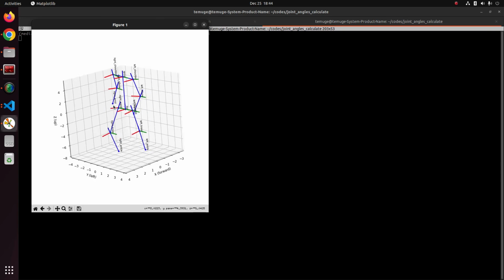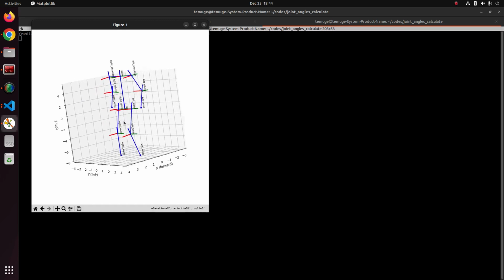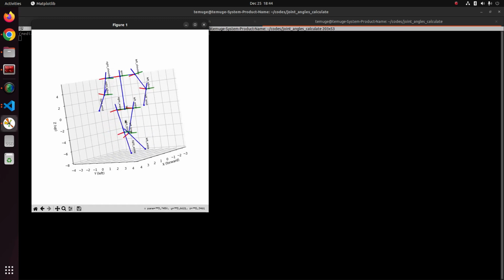Here we can see each joint. The joints are defined with the x-axis pointed forward, and the program outputs the joint angle for each joint as a quaternion. And it looks something like this. Now, one thing to notice is that while it's stopped straight, you can see there are some errors with the pose estimation. So this means we have to do some post-processing to fix some of these joints.